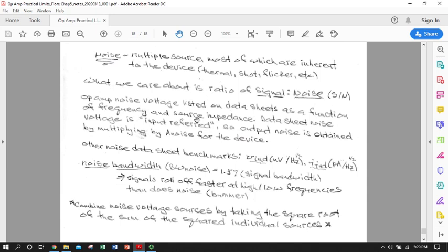From an electronic standpoint, there's basically types of noise signals that are frequency independent, ones that are frequency dependent, and that's only important because that gives us a strategy for getting rid of them. Basically understand that unless you can reject them at the front end with your differential amplifier, your noise voltage sources are going to be amplified right along with your signal. And what you're going to care about in every case is not necessarily the total magnitude of your output signal or the gain for your signal or the output or gain for your noise, but the ratio of the two.